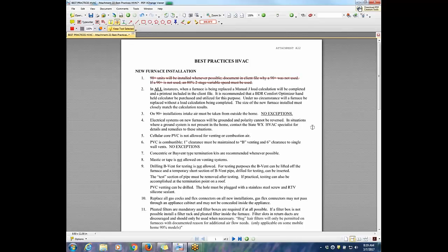Because the thing you need to realize is the audit tool is also sizing your equipment, and if you miss a wall, or windows, or whatever, it starts to undersize your equipment, because the tool is going, okay, the house is only so big and there's only so many exterior components. If you're doing the audit right, I've compared the NEAT audit to the manual J, and 95% of the time they're so close it's no big deal. Our field guide says manual J or equivalent, so I think that's covered in the field guide and doesn't need to be in here.